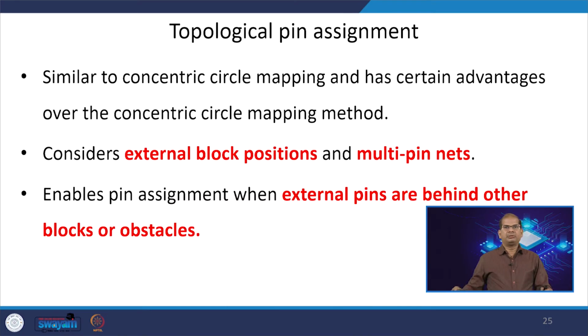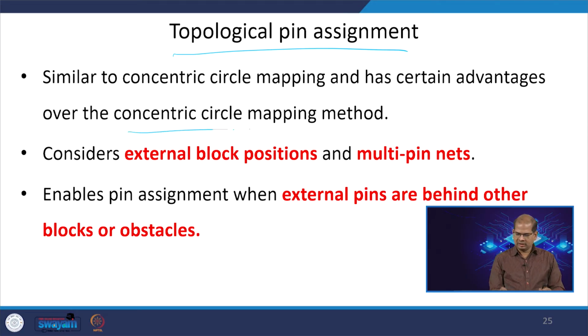Now, we have discussed the concentric circle approach. Then we will go into topological pin assignment. This topological pin assignment has certain advantages over the concentric circle based method, because it considers external block positions.